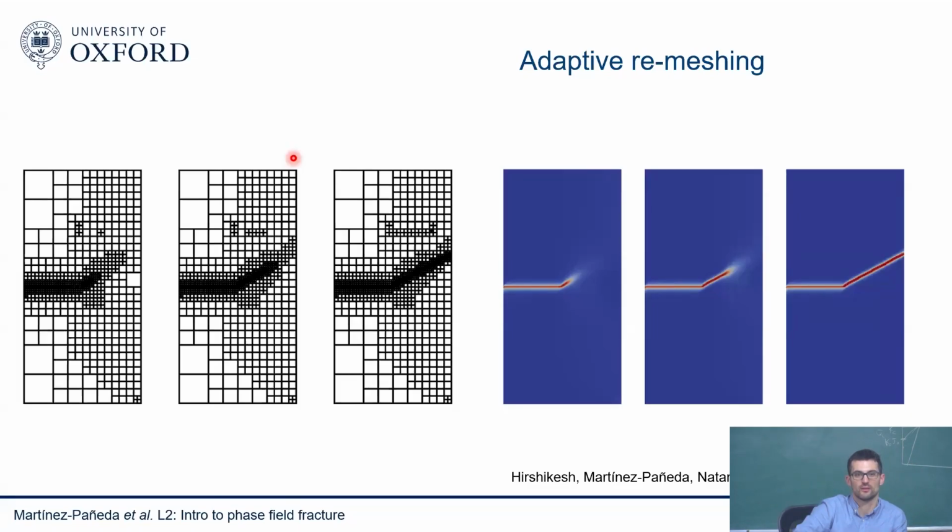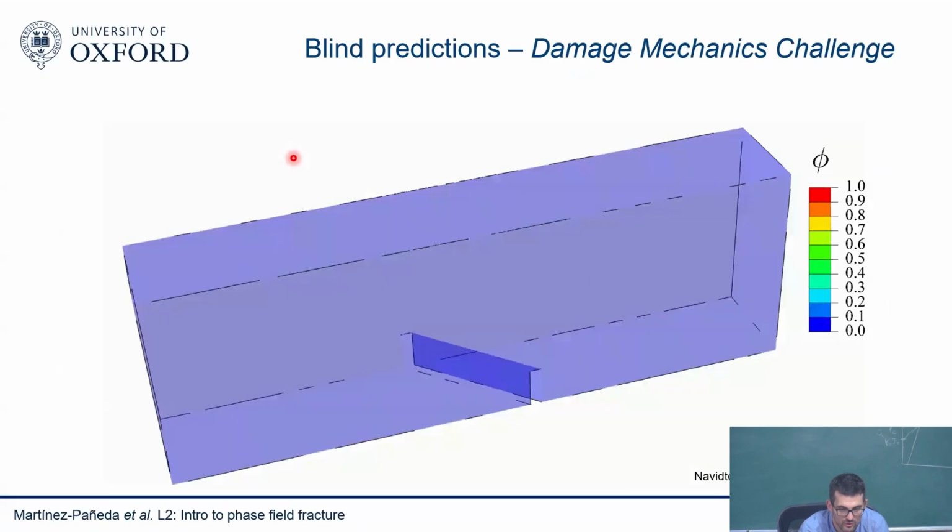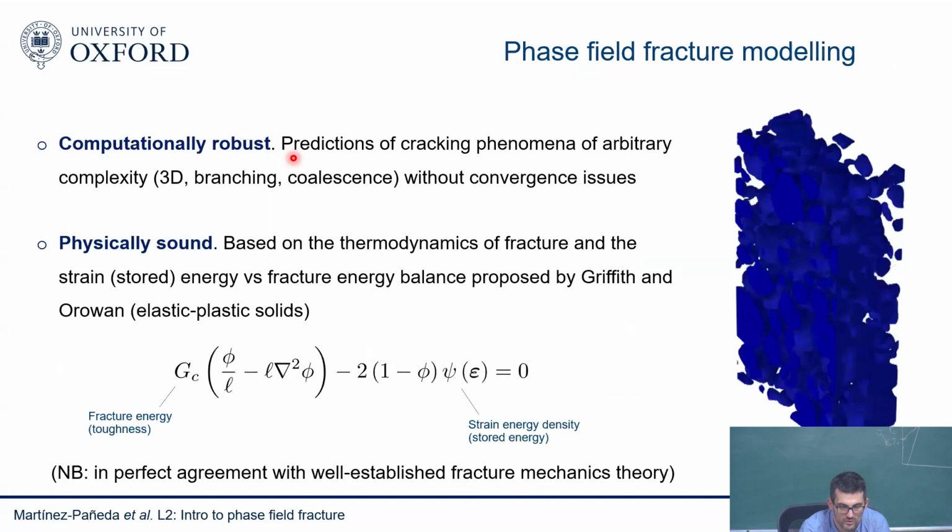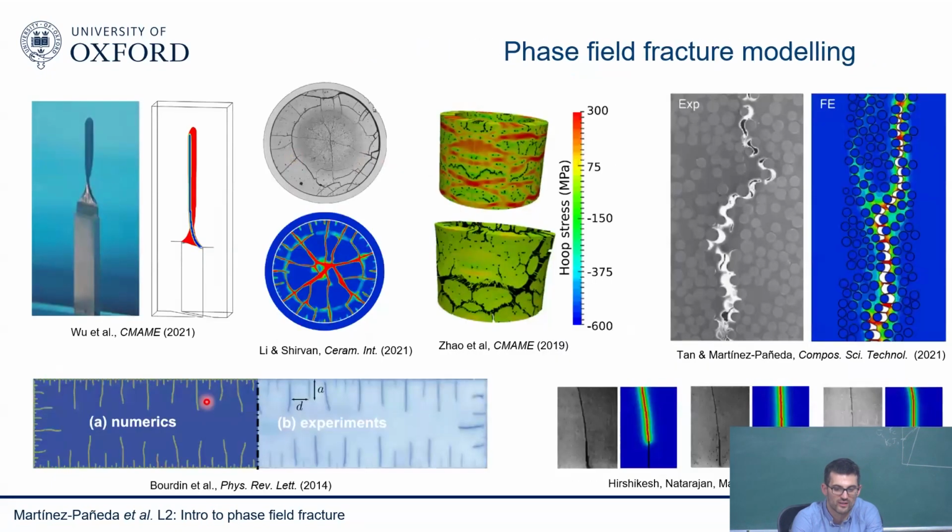Yes. So there's nothing, that's the beauty of it. You don't have to do anything. You're solving for the phase field. So if it's energetically convenient for a crack to nucleate, let me show you some examples. This one is quite remarkable, this thermomechanical experiment. This is thermal shock, so you have something at a high temperature, you put it into a bath at room temperature, and then cracks initiate, and the spacing is related to the change in thermal load and so on. And you can see that the experiments and the model agree quite well.